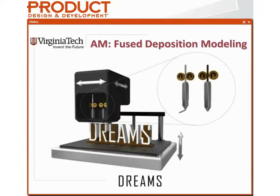So one way, probably the one that you're most familiar with, is fused deposition modeling, first patented by Stratasys. In that process, the way it creates a layer is through what we sometimes refer to as a robotic hot glue gun. Basically, it's a thermoplastic filament that's being extruded selectively. There's a filament being fed through counter-rotating wheels. It's being melted and then drawn to create that one layer. Then on an elevator, that elevator lowers, we draw the next layer, and we continue from the bottom to the top.